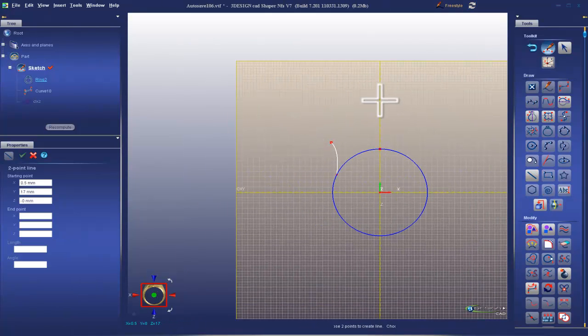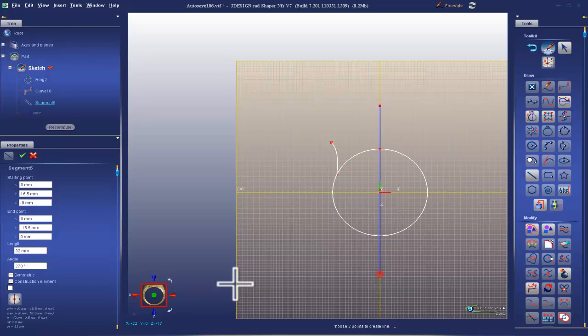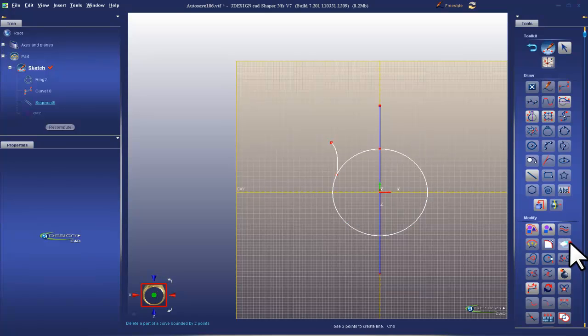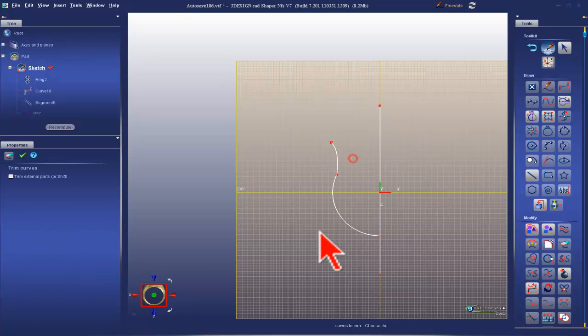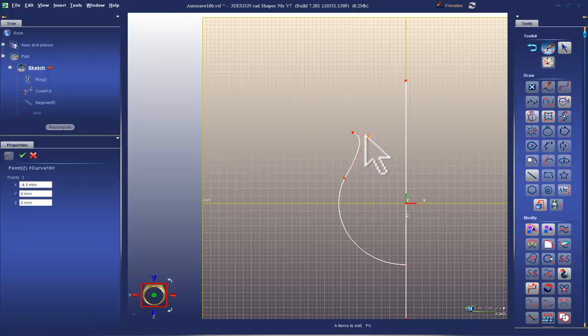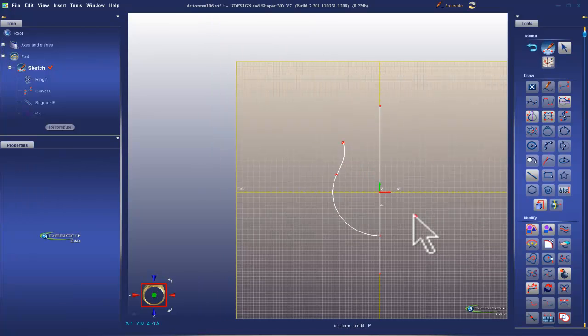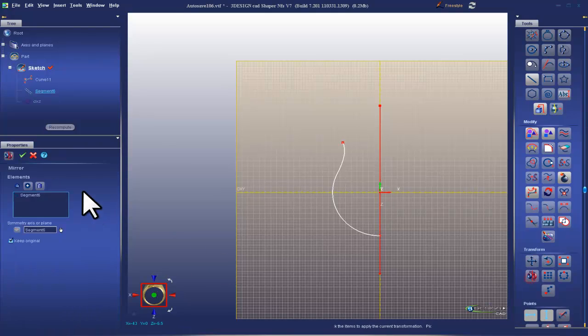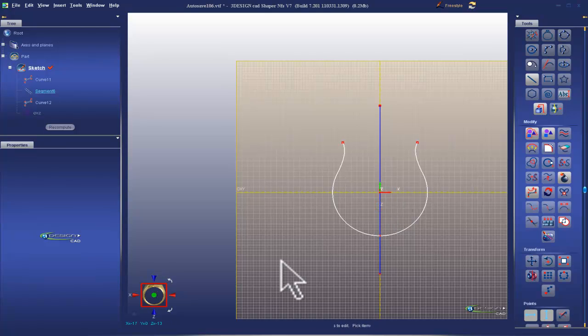So let me go in here. I'm also going to put a cut curve down the middle because I only need half. My grid snaps are on. So I'm going to trim away the half that I don't need, like so, and trim away that quarter. And now I can play with, get the tangency correct. Like that should work. And then finally I'll auto connect, and then I will mirror over that segment like so. Great.